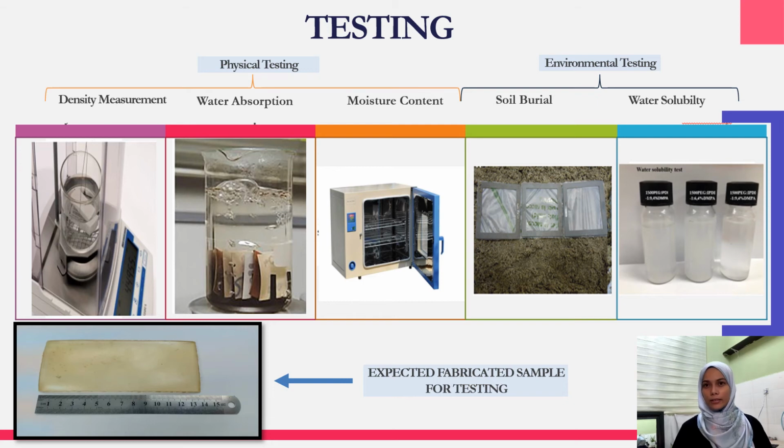And then lastly, for the water solubility test, the sample must be dry and then immersed in water and then stirred. And then the stirred sample is left for about 8 hours and then dried again, and then it will be calculated by the formula referring to the previous studies of other researchers.